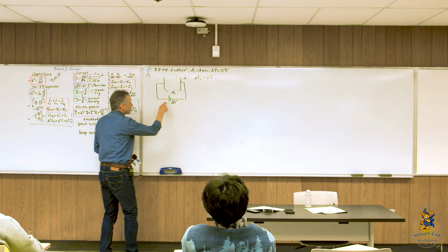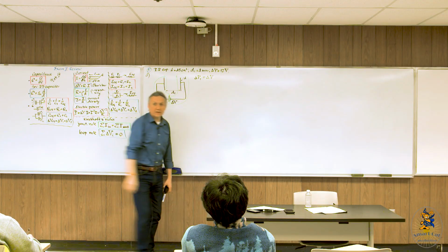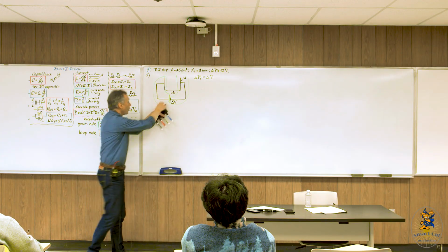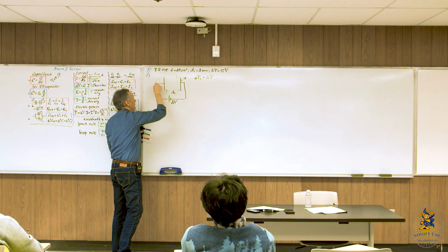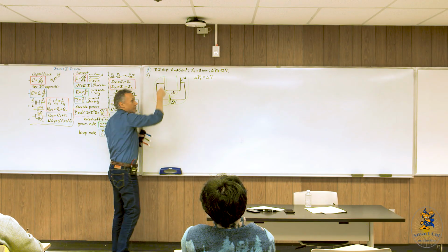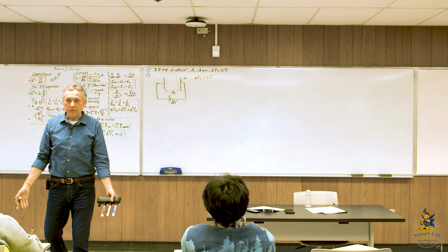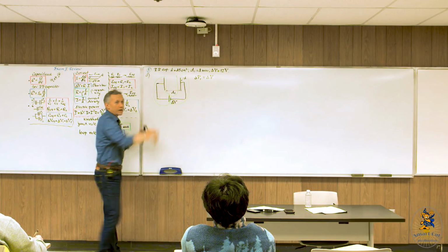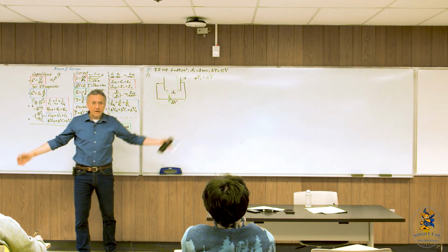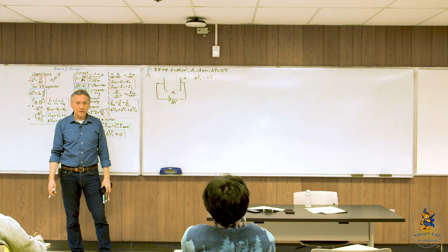So it means that if this electrode of the battery is, let's say, at plus 6 volts, then all these points, and even here on this electrode of the capacitor, will be at plus 6 volts, right? Because this capacitor is fully charged, so current stops running, so this piece of metal is in the state of electrostatic equilibrium.